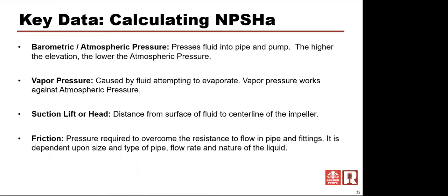But if we have a pump mounted, say, 200 feet away from a tank, and we want to move 400 gallons a minute through that pump, which means we need to get at least 400 gallons a minute into that pump, is there going to be so much friction loss in that 200 feet of pipe at 400 gallons a minute that we're not going to get enough flow into that pump? So we have to take friction losses of that pipe at that flow rate, or hopefully greater, into account when we start figuring out how much NPSH we have.